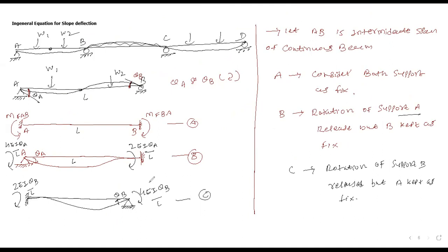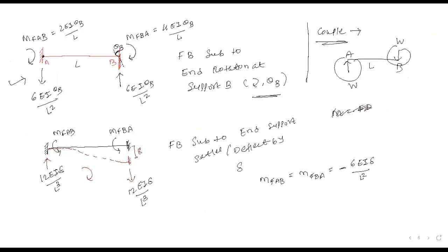Sir, I have one question. बोलिए. At the second support, whether roller or hinge, wherever we rotate, the equation will be 4EI theta B by L only? Whatever support you consider, just understand the previous case. What we have visualized in this case is that your support B is free to rotate by some angle theta. Right? That means the fixity will be somewhat loose. ऐसा बोल सकते हैं.